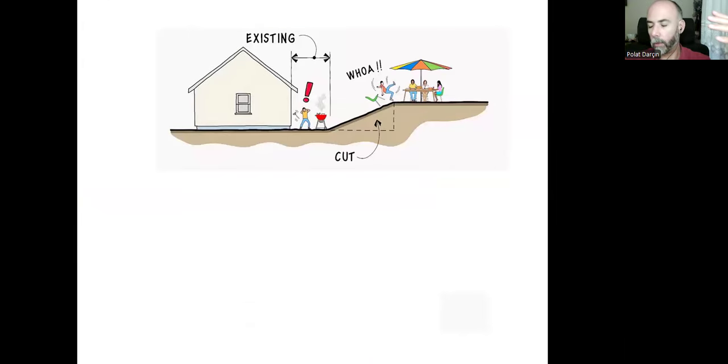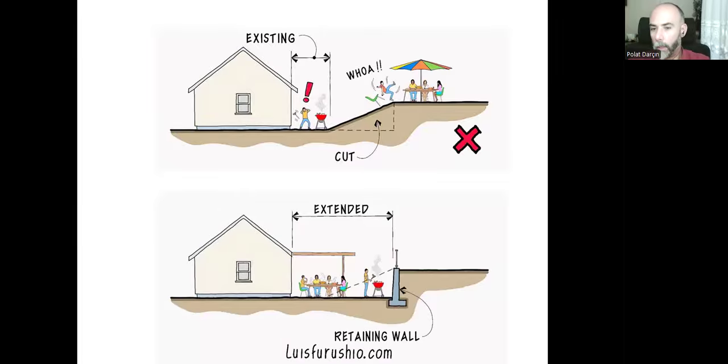Even if we don't do the excavation for the foundations, we just want to have an open unit like this. The sloping natural surface can be dangerous or unusable, unfitting for us. So instead of this risk, we can have a straight surface, and because of this level difference, again, we will be needing retaining walls like that. And that's what we call site grading. We can change the slope of our site based on our design.